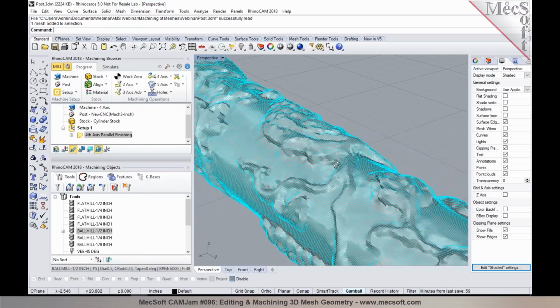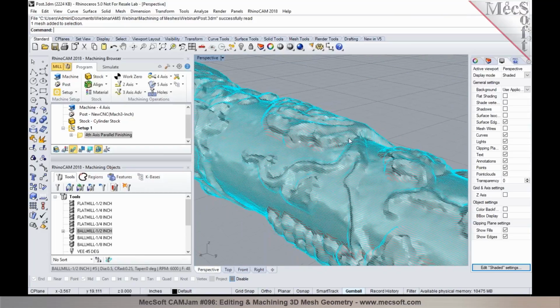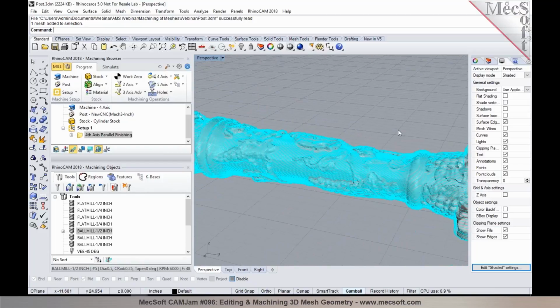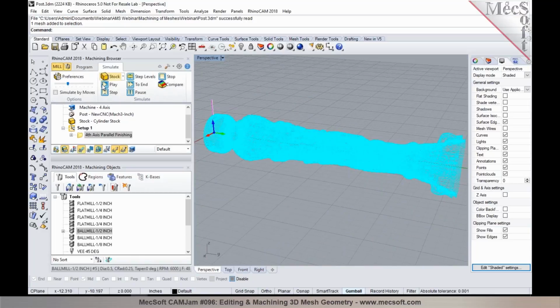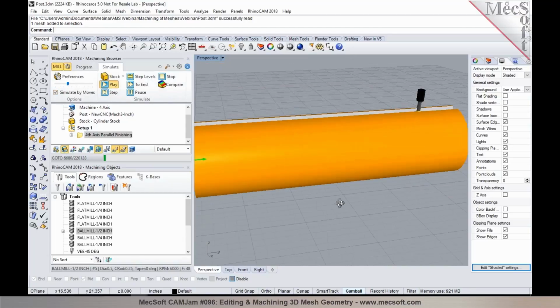So even though it's the same amount of detail, if you have long skinny triangles like in the original model, when you actually machine it, you're going to end up with a bad surface finish. That's why this refinement, where we are reducing those triangles to triangles that have very similar aspect ratio, matters. By that I mean the lengths of the sides of these triangles are about similar. You will get a much better finish.